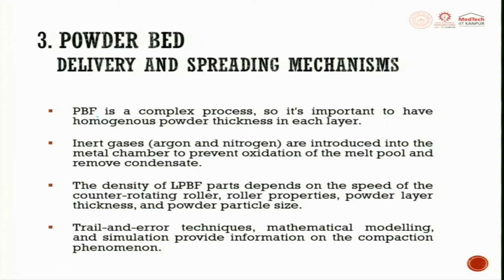The powder bed fusion is a complex process. So it's important to have a homogeneous powder thickness in each layer, because whatever powder gets fallen down, it has to be spread. It has to be spread by a doctor's blade or by a recoater to maintain the uniform thickness.